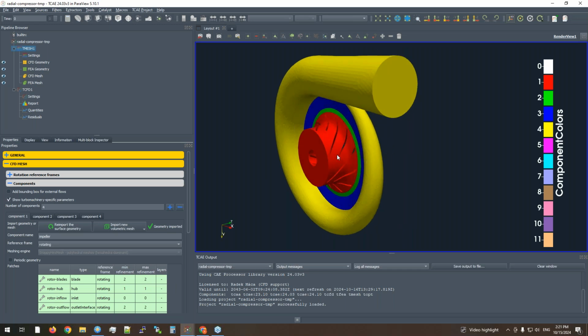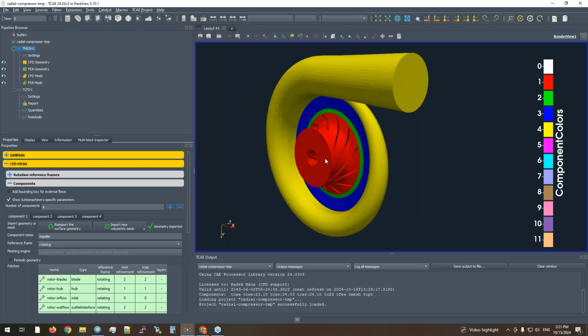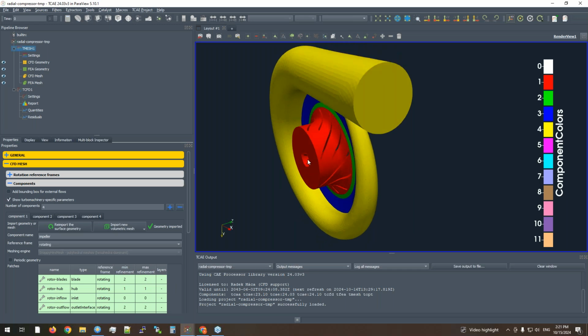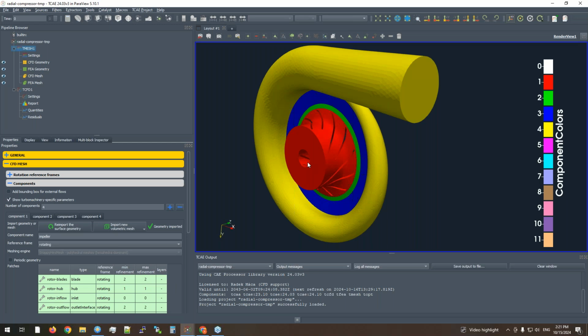So typically the flow goes perpendicular to the inlet patch, if not set in another way. But in this case, we have the total pressure inlet, so we can see that it's too close to the rotating part, so the physics or the real flow at this part is not perpendicular. It starts to rotate right near in some neighborhood of or in front of the impeller.